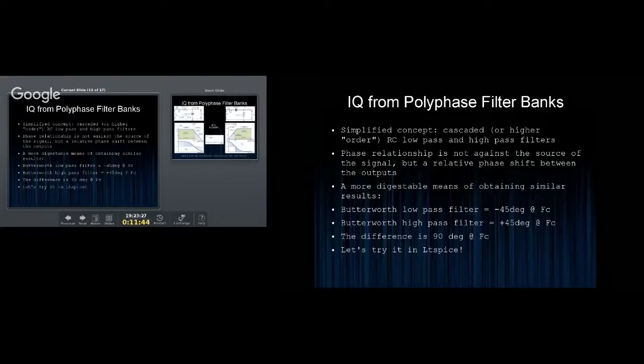So in that particular instance, you've got +45 degrees from one filter and you've got -45 degrees from another. What if you cascade them? In the last case, I've got 4, and each filter contributes 12.5 degrees. The great thing about doing this is that you end up moving your operational point more into the pass band of the filter, so you're not attenuating the magnitude quite as much.